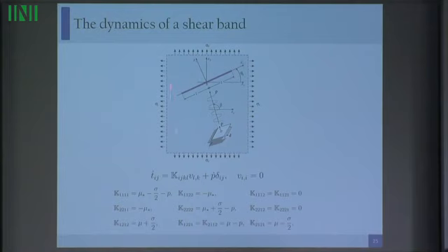So for the material of the infinite body, we use incremental elasticity, the so-called J2 deformation theory of plasticity. It's a nonlinear elastic law which mimics the behavior of a plastic material. These are the constitutive equations.